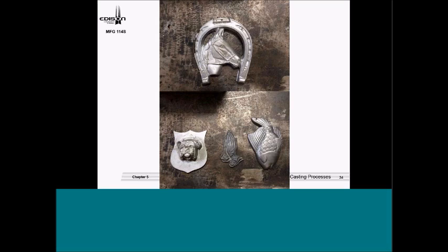And what I'll end up doing, I want you to picture this being in the bottom half. And as I look at it, before they button it up and put the sprue and the riser in, I want to see the runner and so on and so forth, and it looks like we've got it steep enough. We may have to have 2 runners going to the riser, 2 runners leaving from the sprue, just because of getting enough metal into the cavity itself. It wouldn't take very much metal in this one. There are times when I will put more than one pattern in the flask itself. So sometimes the students will work together and they'll just put runners across each pattern.